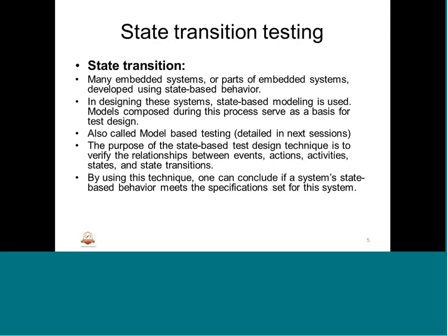Many embedded systems, or parts of embedded systems, are basically being developed with the help of state-based behavior. This is something at different modes, where the embedded system will move from one to the other. That means it has a predefined set of actions or executions for such a mode or such an event. So based on the criteria that it enters, or based on the criteria that it exits from that particular state, it has a number of behaviors that it has to perform.